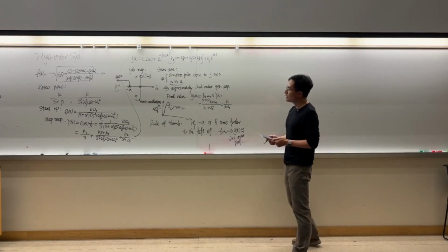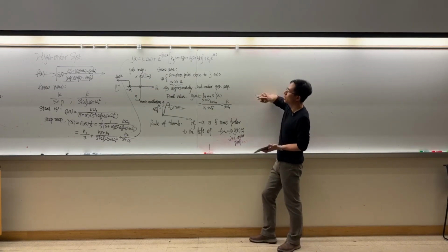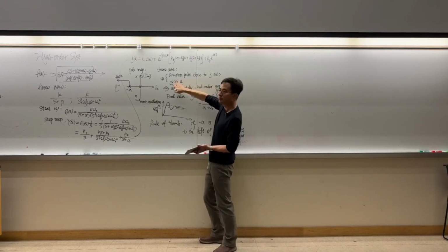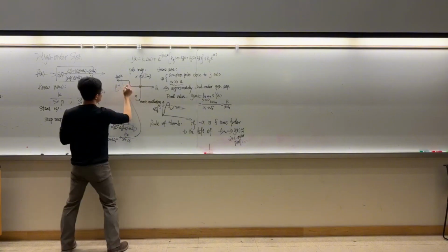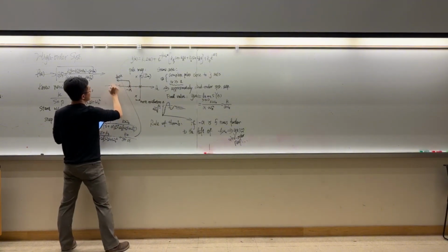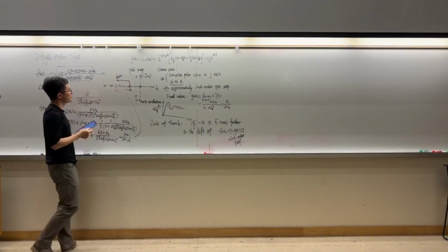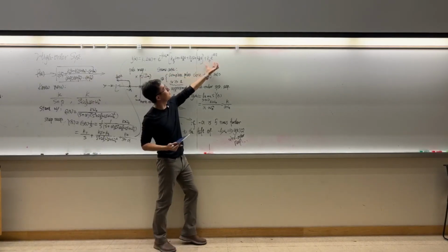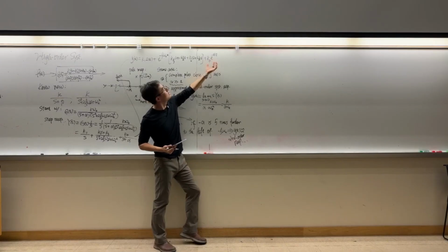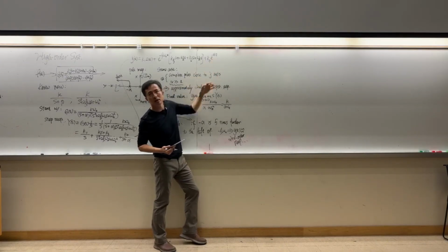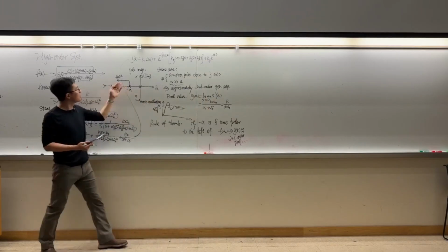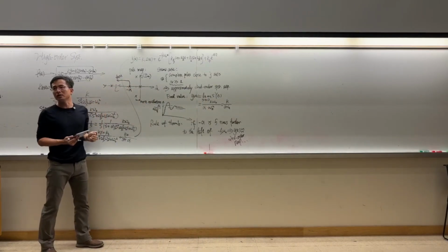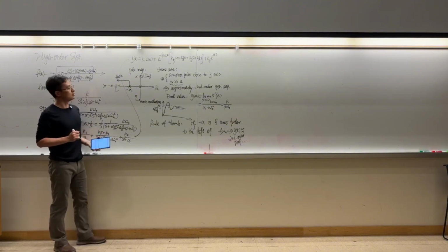So that's the first scenario, the concept of dominant poles. If there are many more poles like these, then similarly you just have more superposition of these modes, and if they are very far away from the imaginary axis, they can all be discarded in the steady state response.